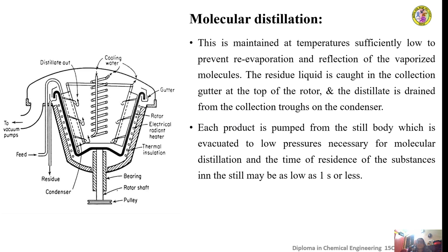So each product is formed from the still body, which is evacuated to low pressure necessary for molecular distillation, and the time of residence of the substance in the still may be as low as 1 second or less. So you can see that a reduced pressure is maintained by connecting the outlet pipe here to a vacuum pump. And the liquid is staying inside the vessel for a very short time of around less than 1